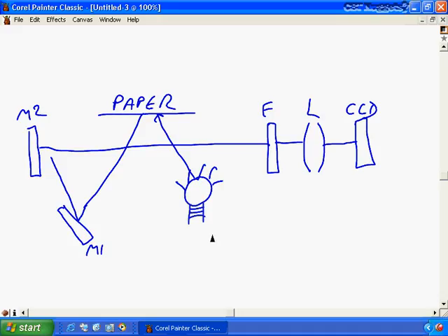And then this light, especially in a flatbed scanner, is going to move back and forth across the surface of the paper so that it can read all the way up and down that paper. How does it move on that? Well, there's going to be a stabilizer bar that this thing rests on, usually about a 1/2-inch diameter stainless steel rod. It's fastened securely to the inside of the scanner, and it provides a smooth ride all the way up and down the distance of that page, and makes sure that there's no stuttering or wobbling as it passes, because that would of course cause problems with our final image.